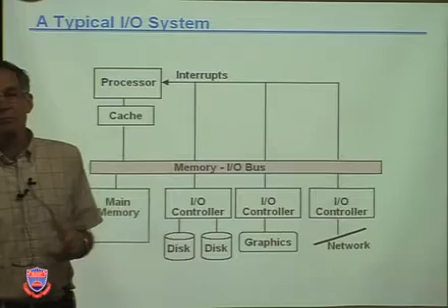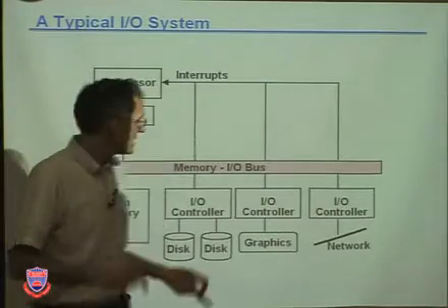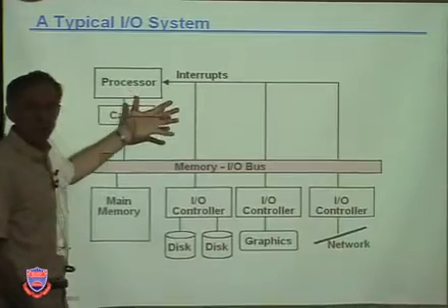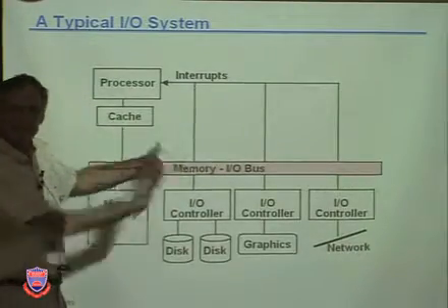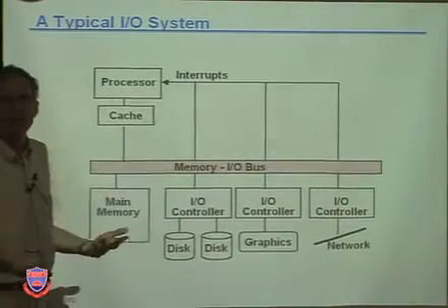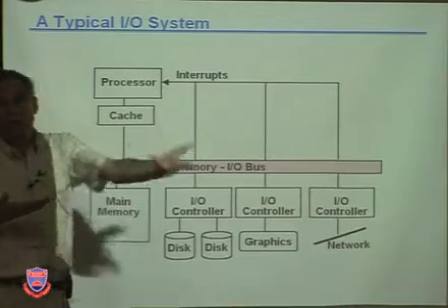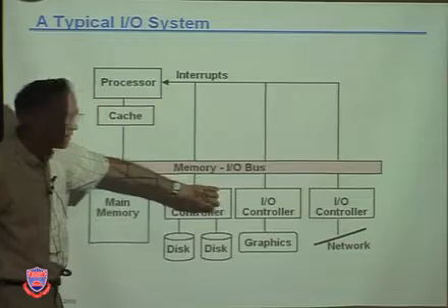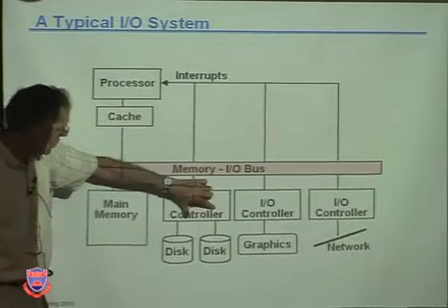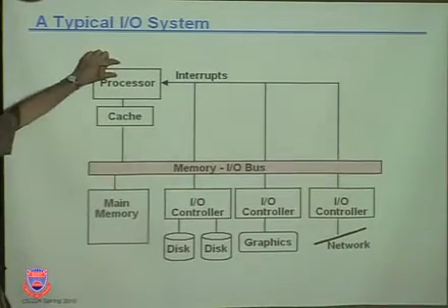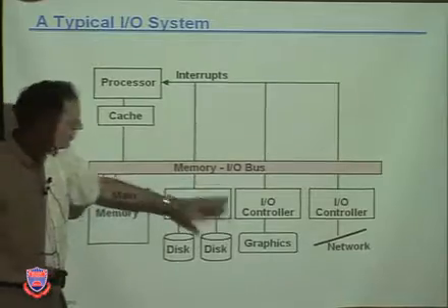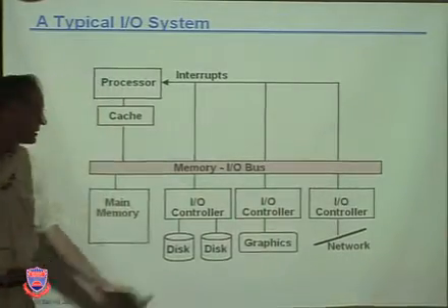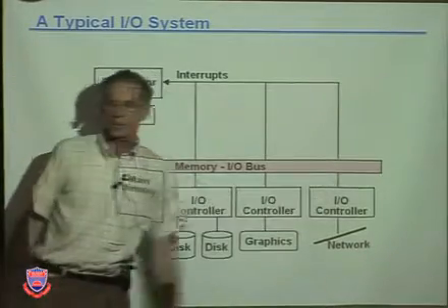And the controller is simply a piece of hardware which interfaces the I/O device to the different levels of the rest of the system, including the physical bus interface and signals and timing and protocol, but also the addressing of its memory items, reading or writing. This is where there'll be buffers, and data coming in from I/O will end up eventually in memory and going to the processor. Data going out to I/O will go first to those buffers and then out. For example, graphics controllers are output devices, disks are input-output, networks are input-output.